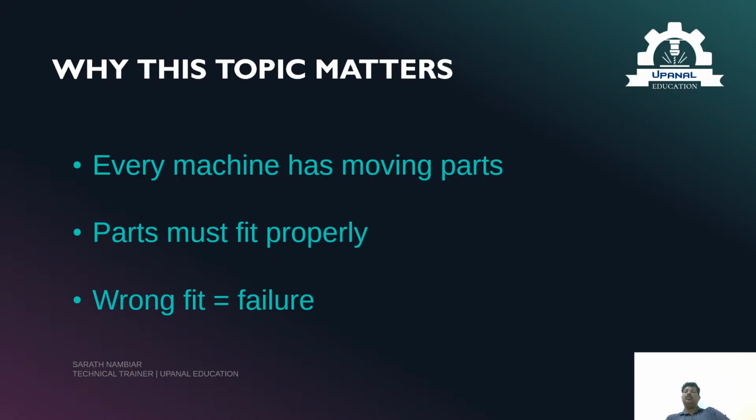If the fit is too tight, the parts may get stuck or may break, or if it is too loose, what will happen? It will cause vibration, noise, and failure. So, this topic is basically not just theory, it is the foundation of mechanical assembly.